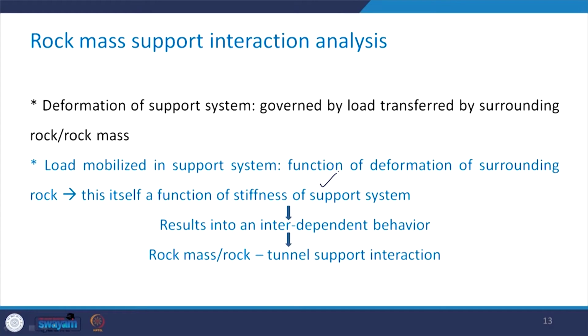So, you should be able to visualize that this whole phenomenon is resulting in an interdependent behavior, and therefore, this is called rock mass or rock tunnel support interaction. Why we are calling this interaction is because of these two statements, that is, the deformation of the support system is a function of the load transferred by the surrounding rock.